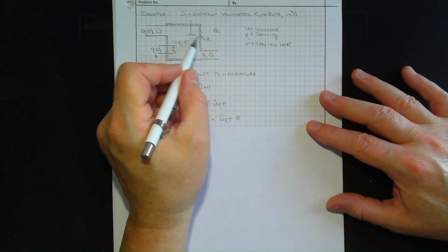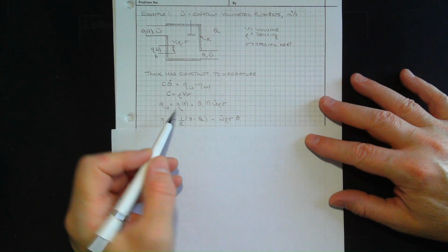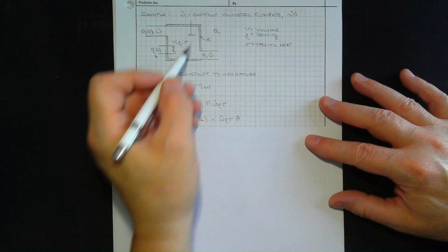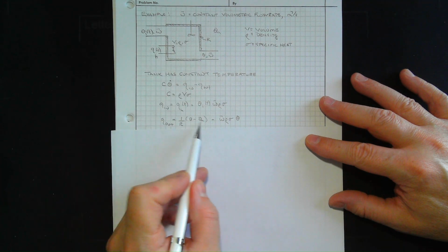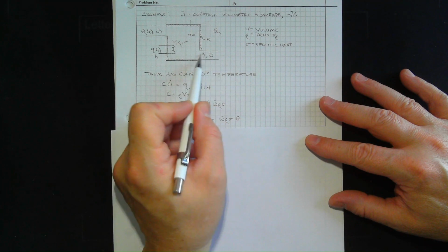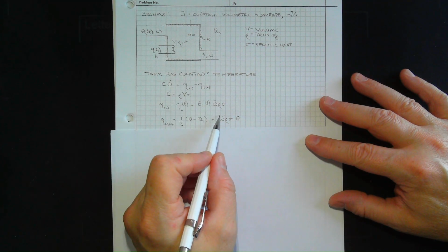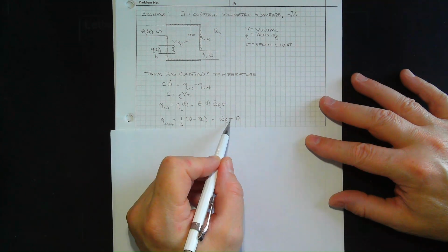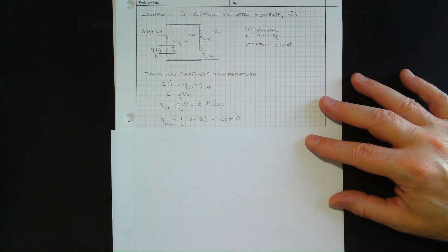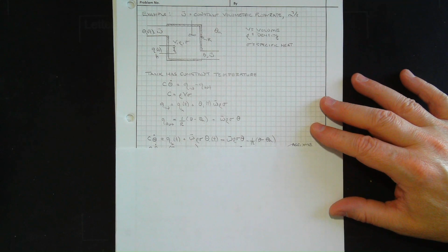And you have heat coming out, treating that as a resistor. So you have the R value of the wall, 1 over R, theta minus theta A, driving the heat out. And then you have the heat in the flow coming out. Again, mass flow rate, these two terms, specific heat and temperature. And there, pretty much you have it. The rest is really just algebra.